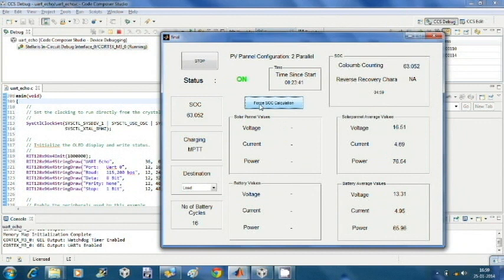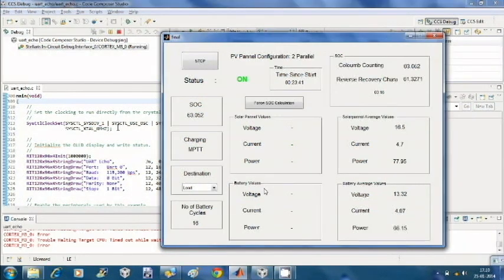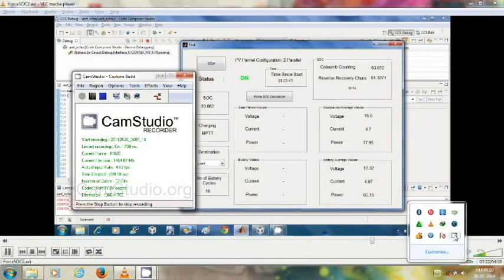The user can force SOC calculation. In such a case, the battery is disconnected, the terminal voltage at the second and fifth minute is taken, Euler characteristics is applied, and SOC is recalculated to calibrate the SOC obtained from the Coulomb counting method. Because the force SOC process takes 5 minutes, the video is fast forwarded.